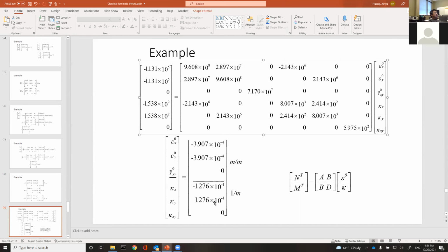You get the stretching and warping. So this calculation predicts that this cross-ply 0-90 degree laminate will warp. It actually predicts which way it'll bend. It'll bend in X and bend in Y. It'll stretch as well. It's not going to shear. Gamma XY equals 0 means it's not going to shear, and kappa XY equals 0 means it's not going to twist. The last term, kappa XY, is twisting. So it's curving but not twisting. It's stretching but not shearing. This is the thermally induced strain.